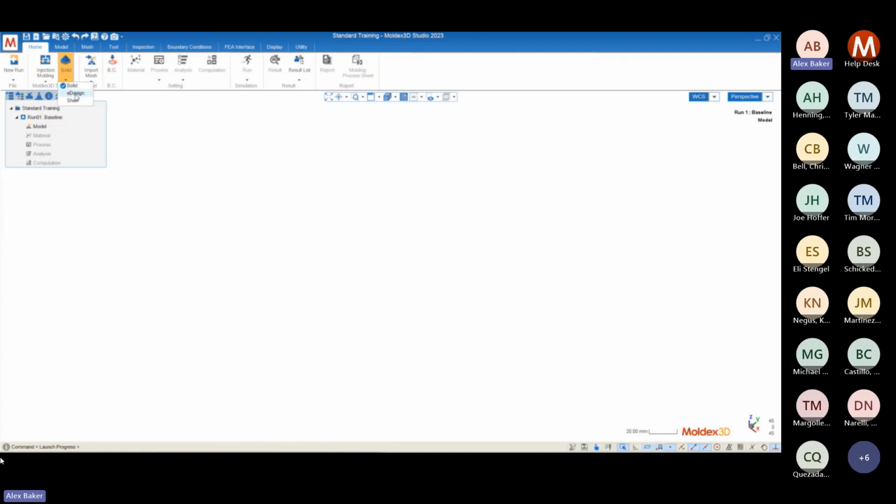eDesign is a little bit more automated. It's not a true 3D mesh. It creates voxel elements that are essentially 3D, but they don't follow the contours of our geometry exactly. And because of that, we have to create kind of an approximated mesh for our mold. So the eDesign strategy is nice for very complex geometries that are difficult to create the solid mesh for using our boundary layer meshing strategy. And that's pretty much the other option that you would utilize.